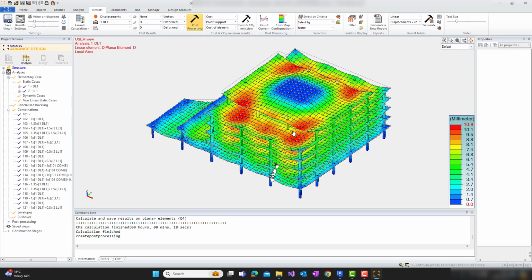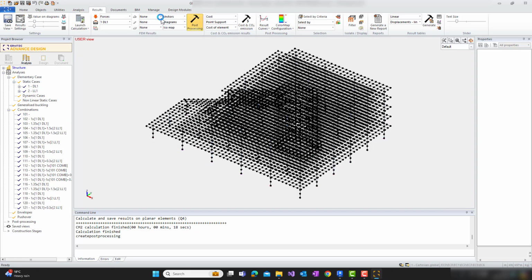Interestingly enough, if we added the beams in here, when we synchronize it back to Revit, we can get it to create the geometry within Revit. So it works both ways. Anything we create in here now, when we synchronize back, if we made any changes, we can update those changes in there as well. Okay. Let's just go back in. I can select the displacements. I could look at the forces. So I might want to check when it lets me into the drop down.